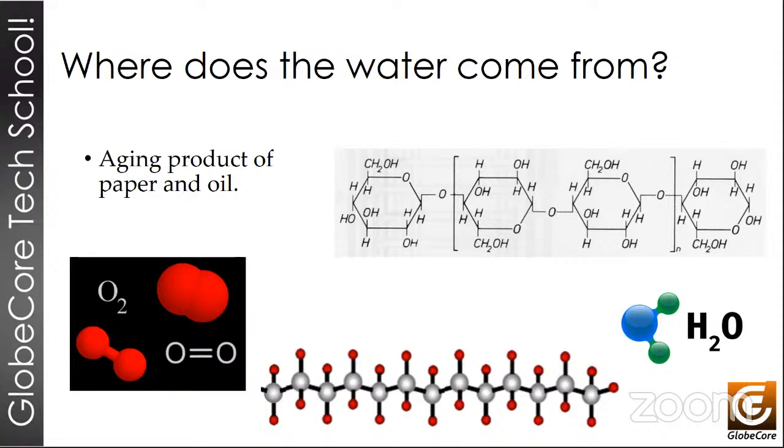During oxidation of oil, water is actually formed as a byproduct. So in this case, you can call it probably an advantage. Oil has a high solubility, so we don't get free water. But oils with high moisture content can foam very much during degassing, and that can be a problem. It's always recommended to process oil to achieve low moisture content before filling the transformer, because the paper insulation system